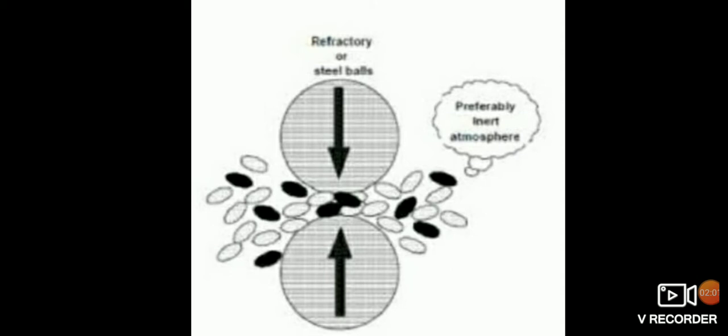Similarly, the serious problems that are usually cited are contamination from milling media and/or atmosphere, and the need to consolidate the powder product without coarsening the nanocrystalline microstructure.